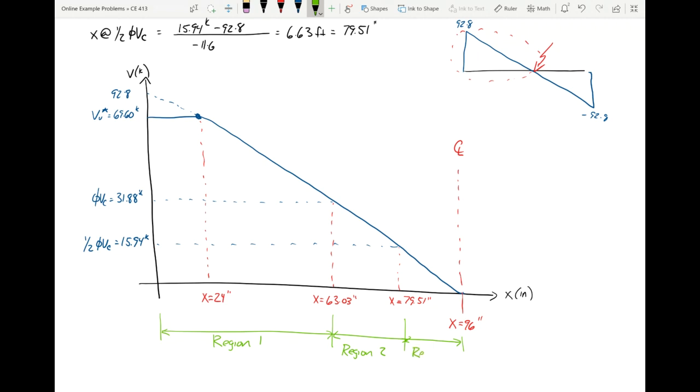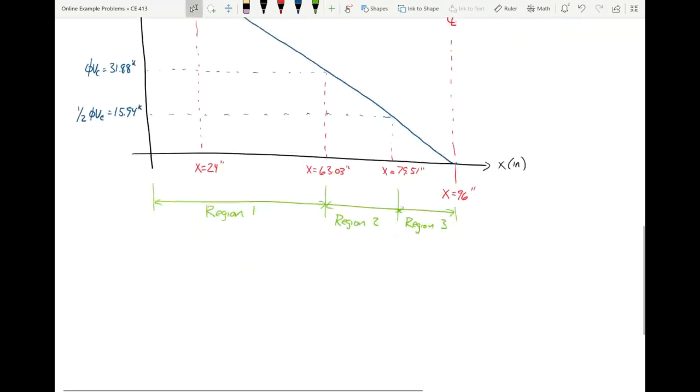And region 3, you shouldn't really be using any stirrups at all. You might have a stirrup maybe bleed over into region 3, but by and large, you shouldn't need any stirrups at all there. Okay.